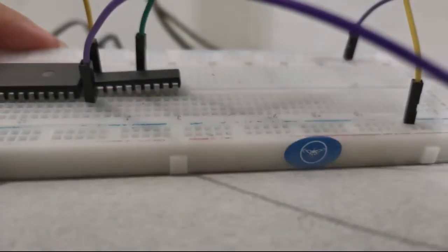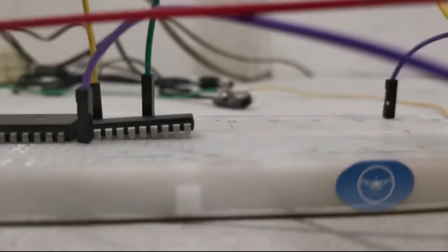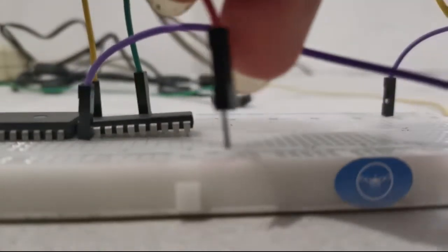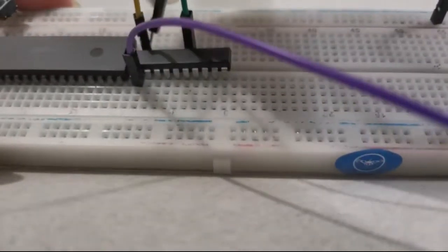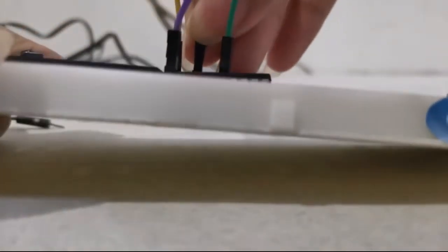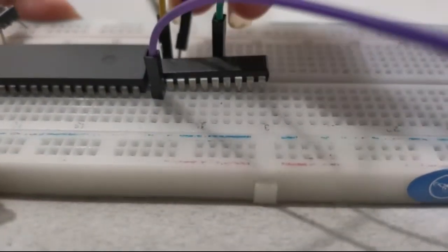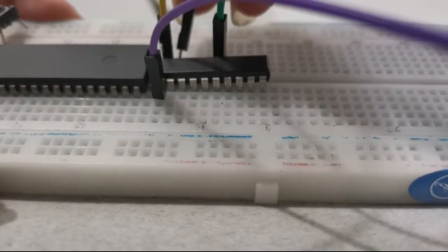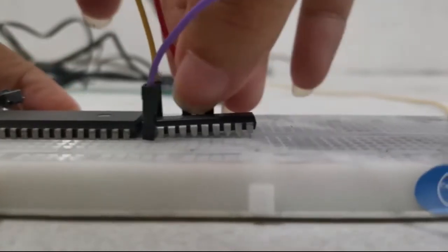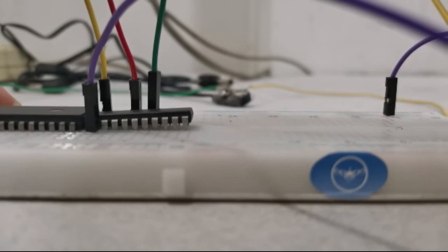And then after that, we now have our potentiometer input in red, and our potentiometer input will be put at RA2, which is right here. Potentiometer input is at RA2. So RA0, RA1, RA2. So RA2 is here. So now we have both our potentiometer and servo motor inputs.